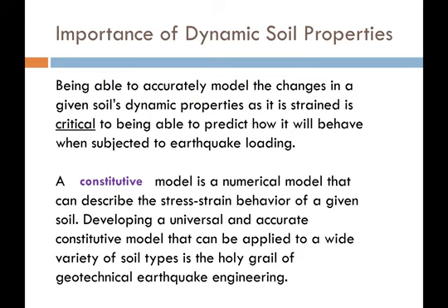And there are numerous researchers and engineers who have spent a lifetime and continue to do so to try to better model the constitutive behavior of soil. When we start talking about non-linear site response analysis, constitutive models are the key to accomplishing that. And a key in the development of constitutive models is our ability to model modulus reduction behavior and the corresponding damping behavior of soil.